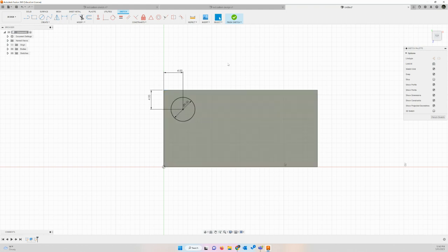So when I do my rectangular pattern, I'm going to start off with a row in my options. Now, I've got 4 pins in a row, 8 millimeters apart. The distance on my rectangular pattern is going to be 24 millimeters. How did I get that? Well, distance from pin 1 to pin 2, 8 millimeters.